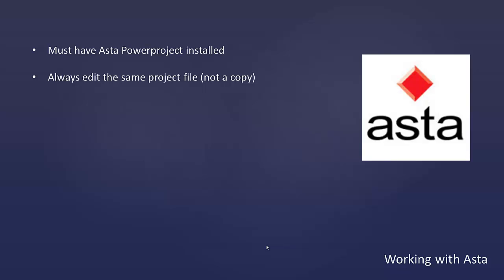This also means the workflow would be import your schedule into Synchro, and if you're only working on synchronize from, you would make changes to the file in Asta and you would synchronize from, never importing twice, never exporting from Synchro to Asta, or you risk having a copy with different IDs. So just continue working with the same file and you have no problems. You can synchronize on a different computer, so if your colleague also has Asta on their computer and they want to do the update for you, or you have Asta and someone else has created the schedule but you want to do the update in Synchro, you can do that. You can send the files back and forth between different computers.